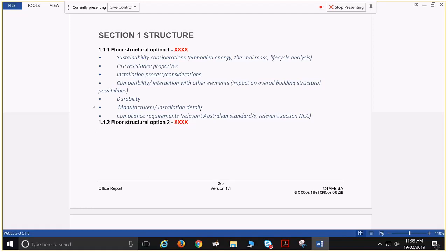However, in Adelaide we have very reactive soil that heaves a lot when it gets moisture in it and pushes things up. If we have slabs that are very long run and it's all a monolithic structure, the reinforcing detail of that slab is going to be significantly different than if we did little individual slabs. And if we have conjoined building elements between those buildings, we're going to have to run dowels between those slabs as well to ensure that they move the same.